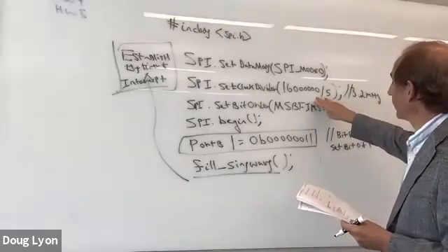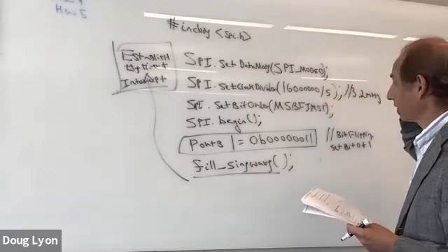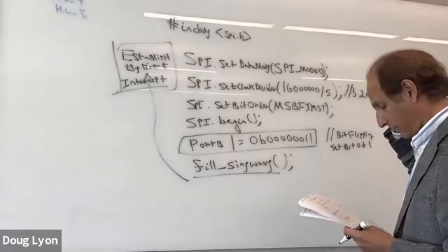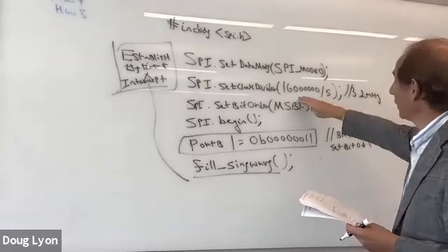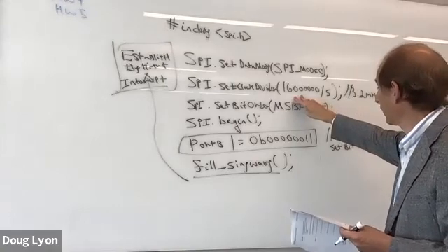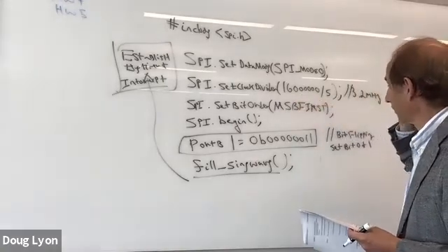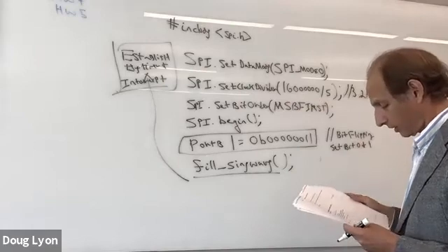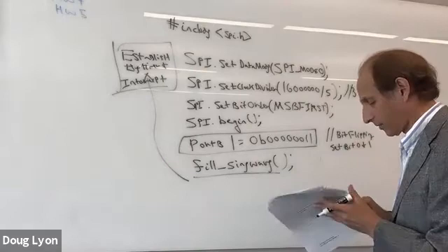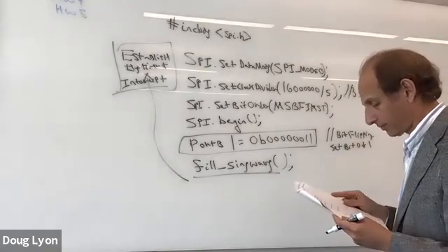Suppose I wanted to divide this by 8. What would the SPI clock rate be? And this is a question that's for question 11. And the answer is if you divide it by 8, SPI clock divided by 8, this is going to be 2 megahertz for an SPI clock. And that's the answer to question 11. Let's see what else we got here.